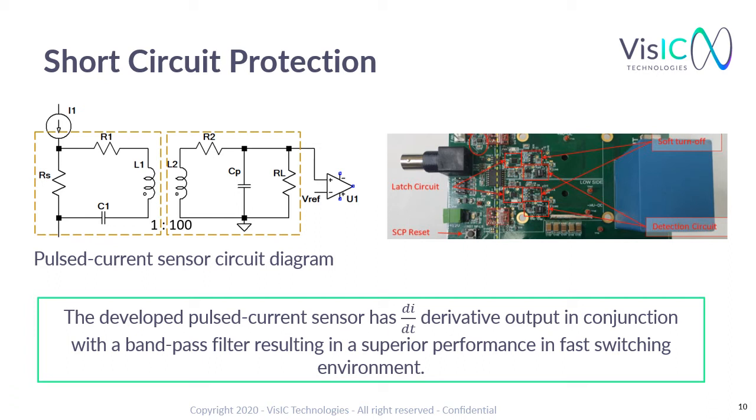On the right, you can see the half-bridge evaluation board on which this circuit was tested. The small transformer and logic circuits take minimal PCB space and can be easily implemented. Once this scheme detects abnormal current slew rates, the GaN device is safely turned off in a multi-gate voltage step approach in order to avoid high drain voltage spikes. Additional information can be found in a paper by VisIC at ECCE 2020 titled Short Circuit Protection Circuit for Automotive Motor Inverter Applications based on GaN transistors.